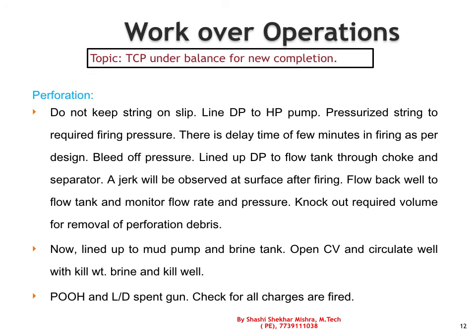Sometimes, if the charge is very small, the jerk cannot be noticed. So then we line up and make the well flow 1 to 2 drill pipe volumes, just to knock out the debris of the perforation and the charge. After the knockout is completed,